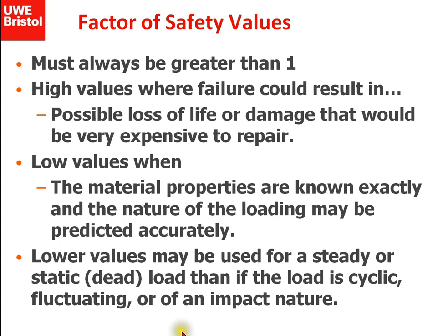Also, we're not doing fatigue analysis or anything like that in this module, but we can imagine that we are going to get repeated loads, cyclical loads, and then you get these things called fatigue stress. So you want to have a factor of safety well above 1, so that these factors, which kick in for lower values of factor of safety, are avoided.